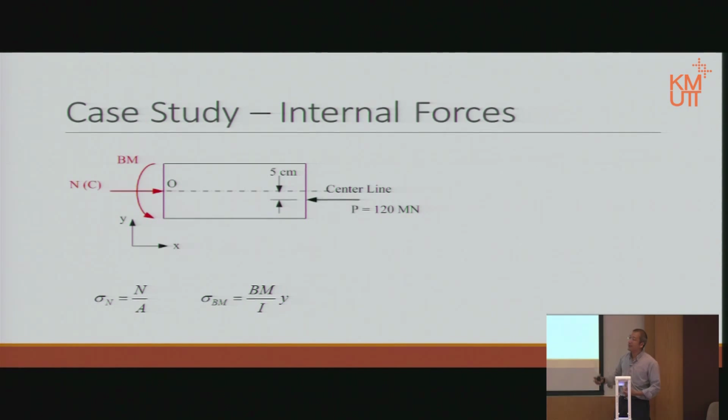So we can see the point load 120 and the axial force N, which, because of the normal distribution, the equally distributed axial stress caused by the axial force, is always on the centroid. And then of course the bending moment will be coming in. For Sigma Fy, if we assume that the beam has no weight or it can be neglected, then of course there will be no shear in this picture.